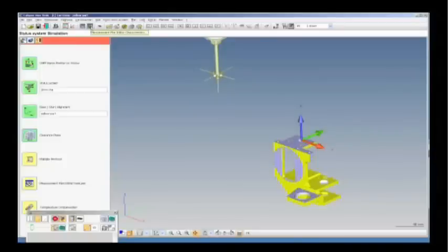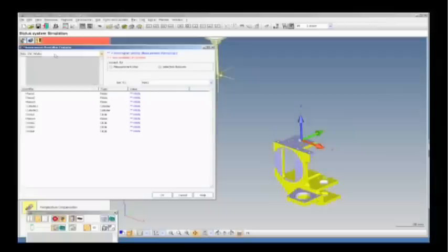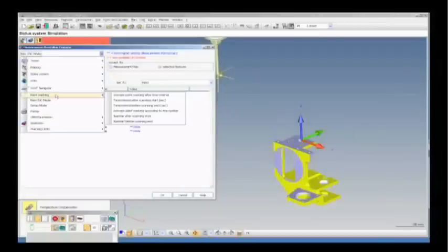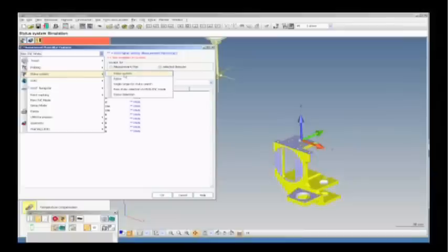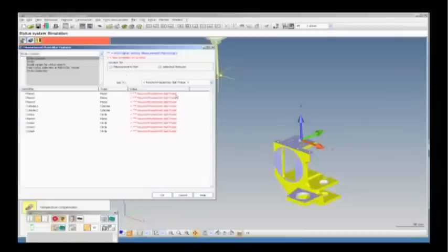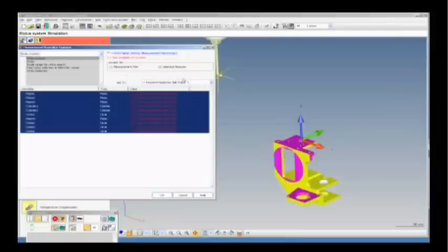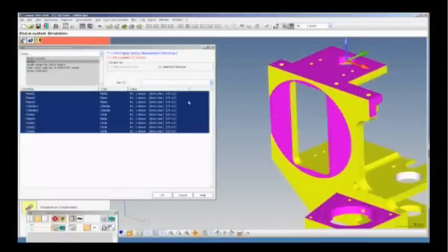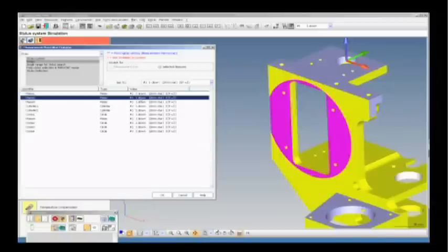So, with that, sorry, I picked the wrong menu here. I can pull up an editor. This is an editor that shows us all the different parameters about the geometry that we've extracted so far. And one of the items that I'm looking at is, instead of using the Faro probe, I'm going to come in and use a star probe. And then from there, all the individual styluses need to be addressed. I can do that manually because I know this front plane needs to use the back probe. So I can come in and select back probe. But realistically, this list is going to be quite long.